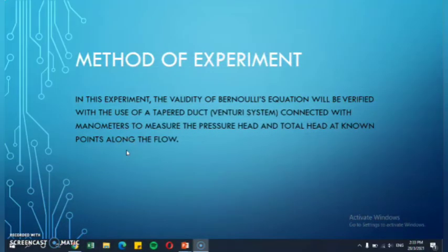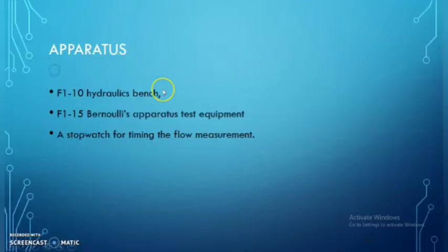Assalamualaikum warahmatullahi wabarakatuh. My name is Yusudin bin Nasir from Group C. I will talk about the method of the experiment. For the Bernoulli principle experiment, we will verify with the use of a tapered duct Venturi system connected with a manometer to measure the pressure head and total head at known points along the flow. The apparatus is a hydraulic bench, Bernoulli apparatus test equipment, and a stopwatch.